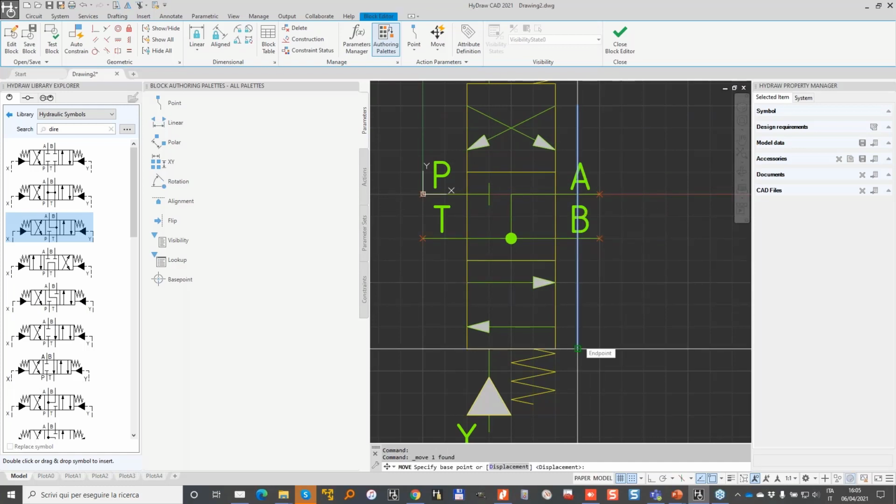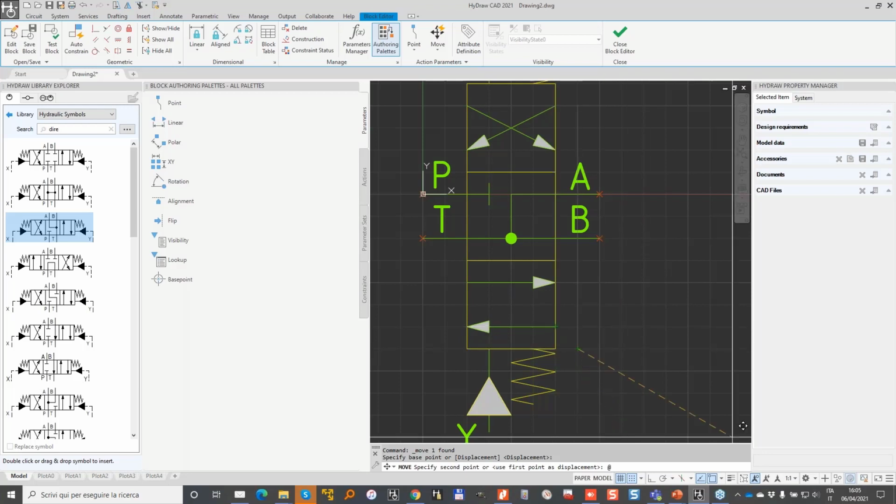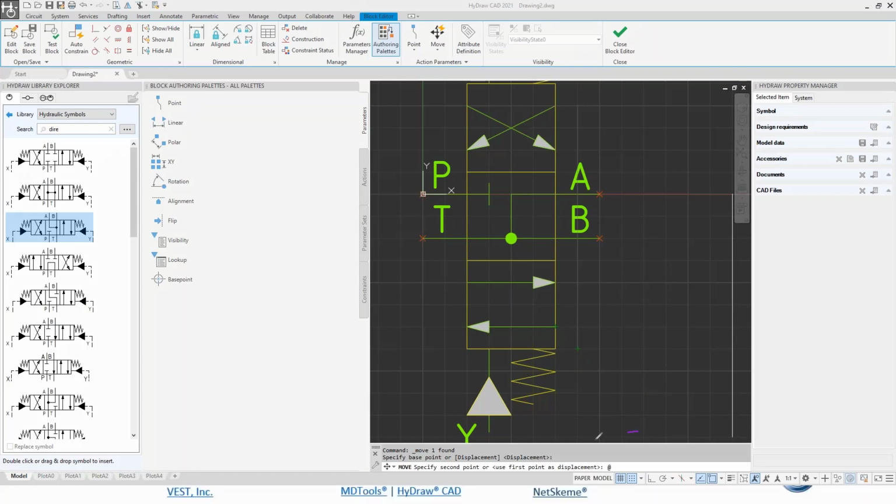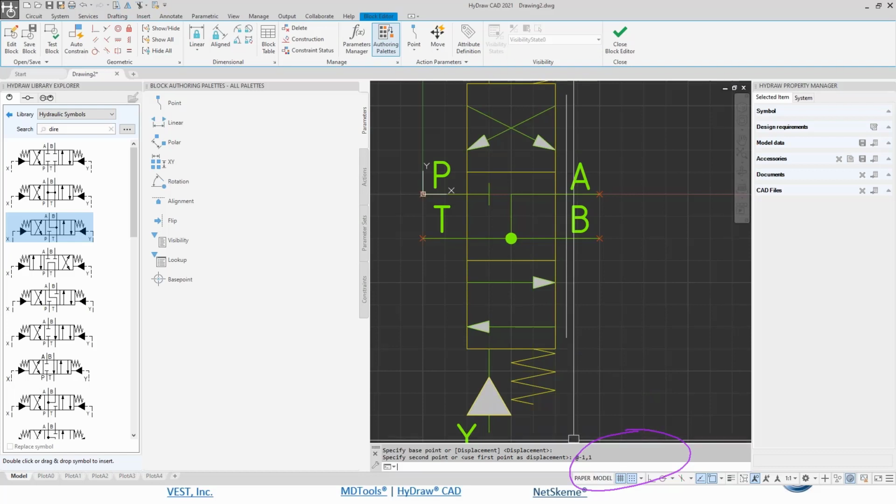If you select the start point and want to move just 1 millimeter left and 1 millimeter up, you can just type @. You see on the command line here, let me highlight it. From the start point, @ means you go a distance of -1 in the X direction, comma 1 in the Y direction, and the line moves 1 millimeter left and 1 millimeter up.